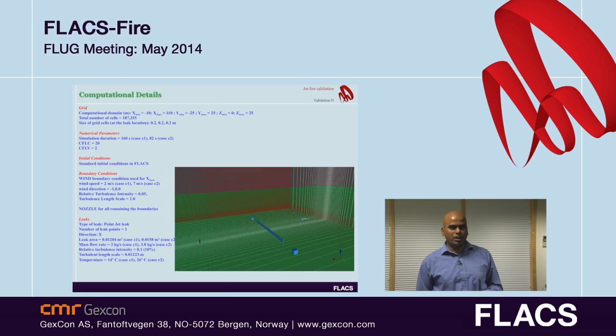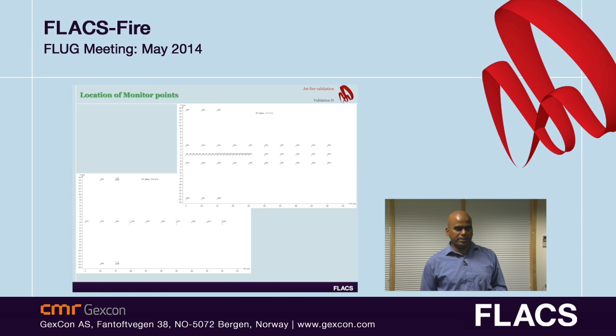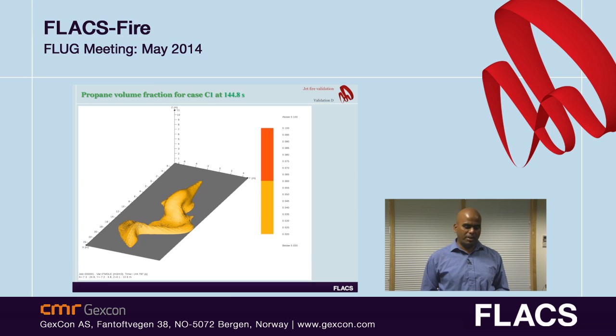These two cases are simulated using FLACS-Fire. The details of the computational domain, the grid size, and the leak details are given here. In the experiment, they measured the fuel concentration at different locations and the radiative heat flux at different locations. So we have used a series of monitor points to simulate these variables.